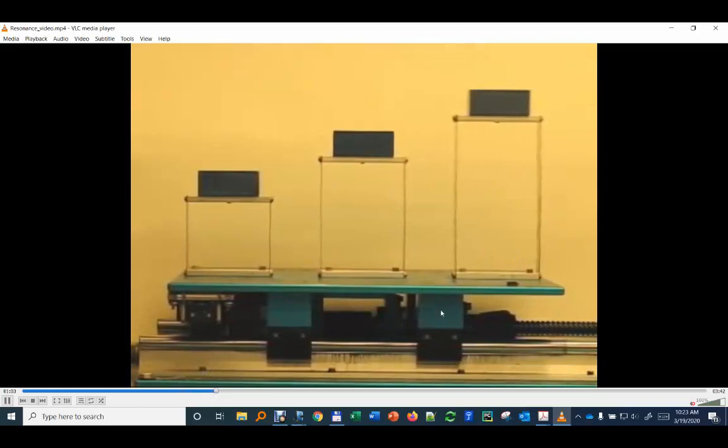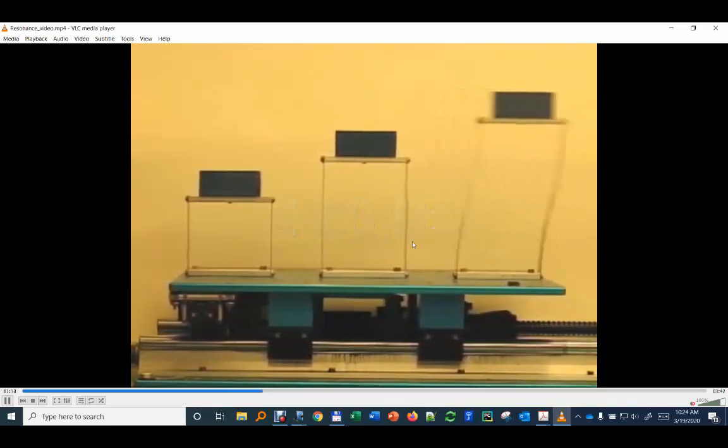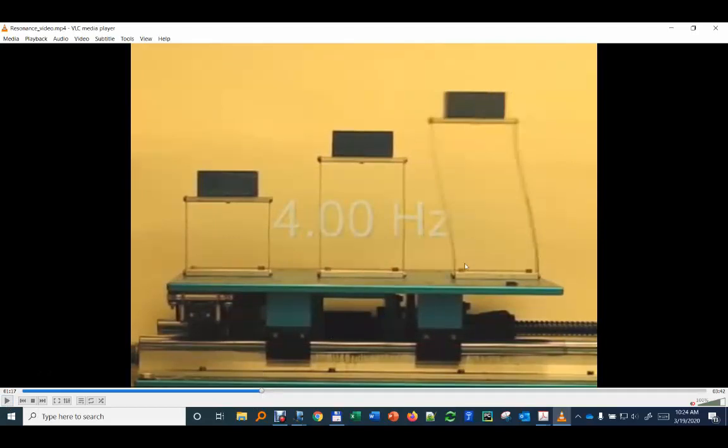Can you see there comes a frequency? If I start increasing that frequency, if I start decreasing the period, you see that you start to have big oscillations on this structure, okay, big movement. So that means that its resonance frequency is very vulnerable at these 4 hertz. Okay, if I excite this structure with 4 hertz, it is going to exhibit maximum amplitude, maximum movement, and we probably will have also big stresses.